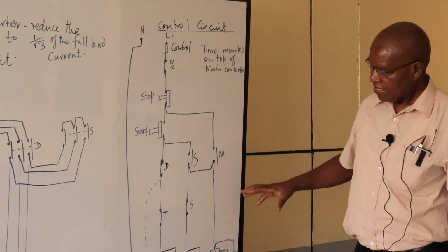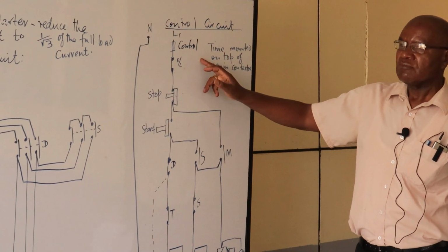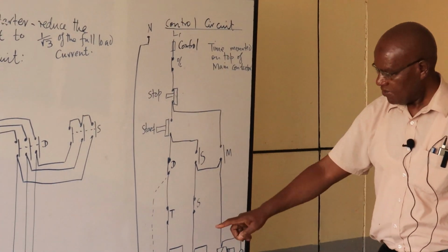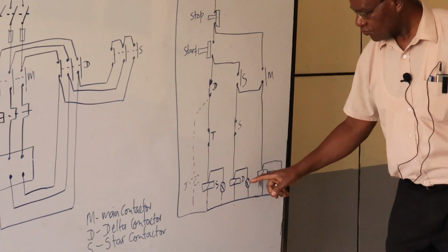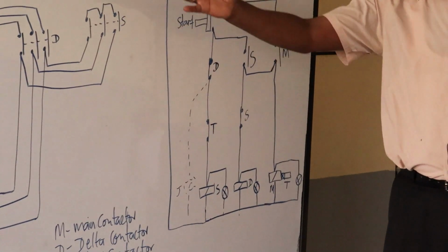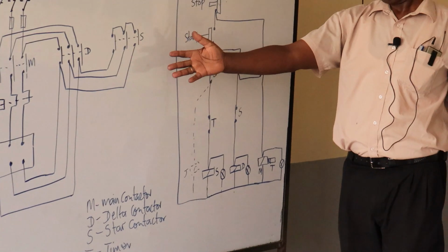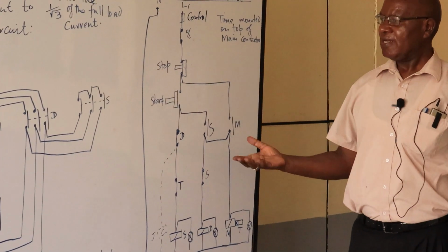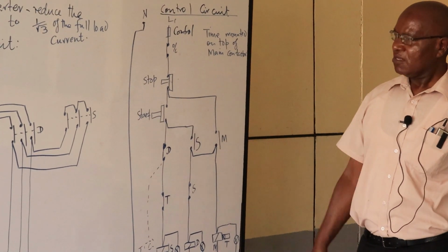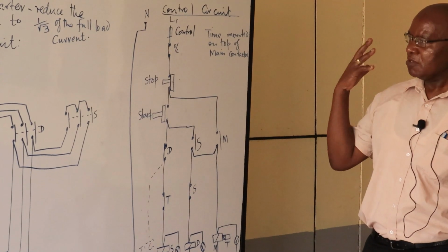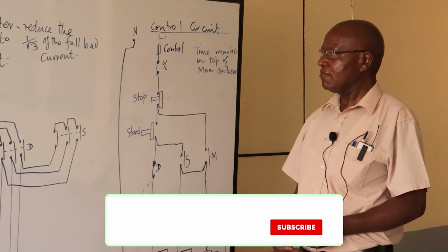Now, of lately, I've seen some circuitry, mainly Chinese, and what they do is that these control circuits here they run on 24 volts. That means these contactors here will be operating on 24 volts, but they can switch our AC. So the design is entirely yours. You come up with a design. But the principles basically remain the same.